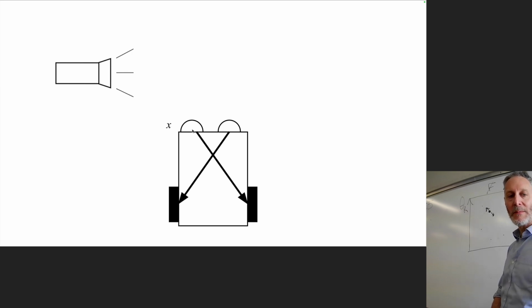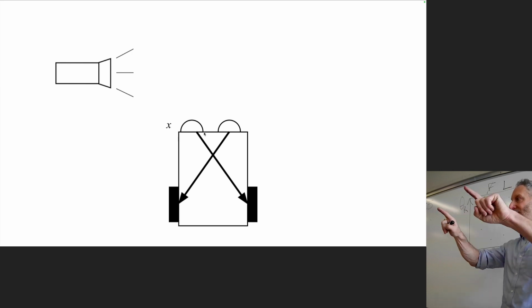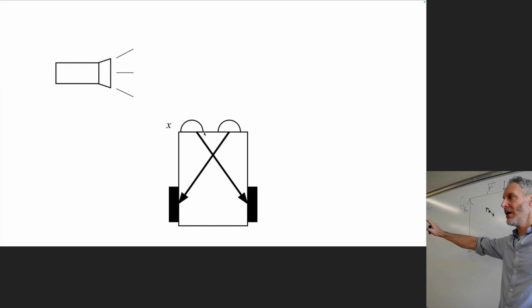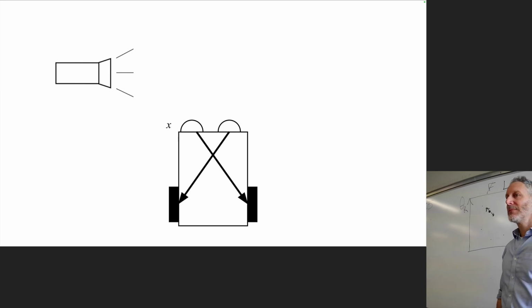You'll notice also that in this robot, the horizontal difference between the two light sensors is greater than in this one. What does that mean? It's actually helpful for this kind of vehicle to have the two light sensors horizontally separated. Why? It's more sensitive to light on either side, and especially light on the left side. What happens in that case? It'll turn quicker.